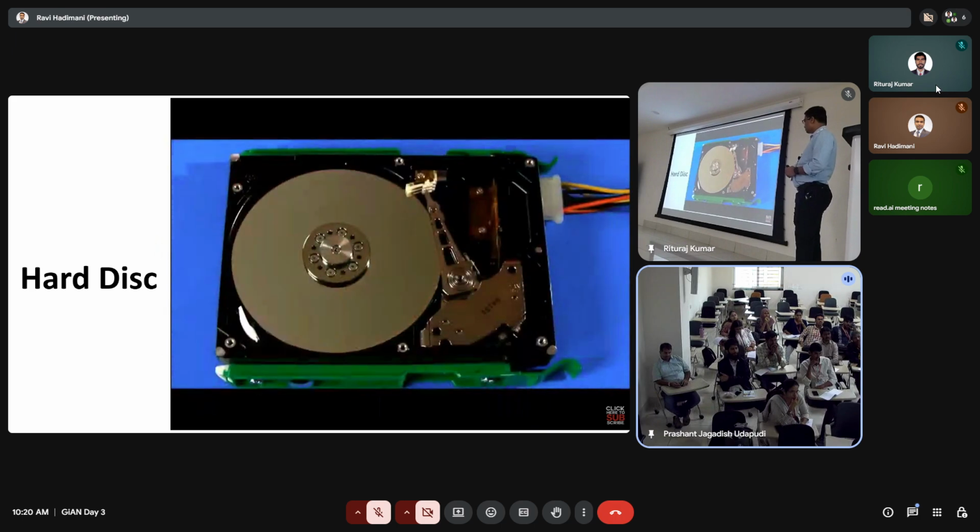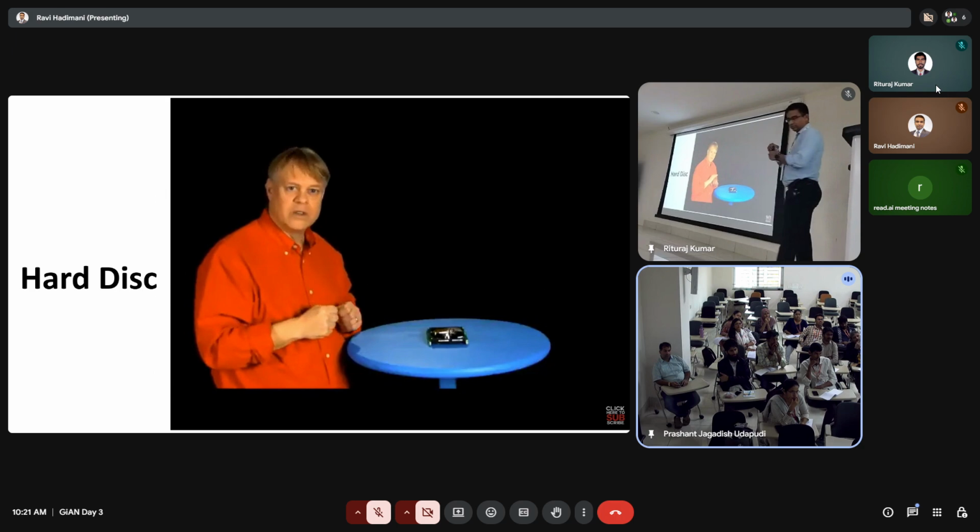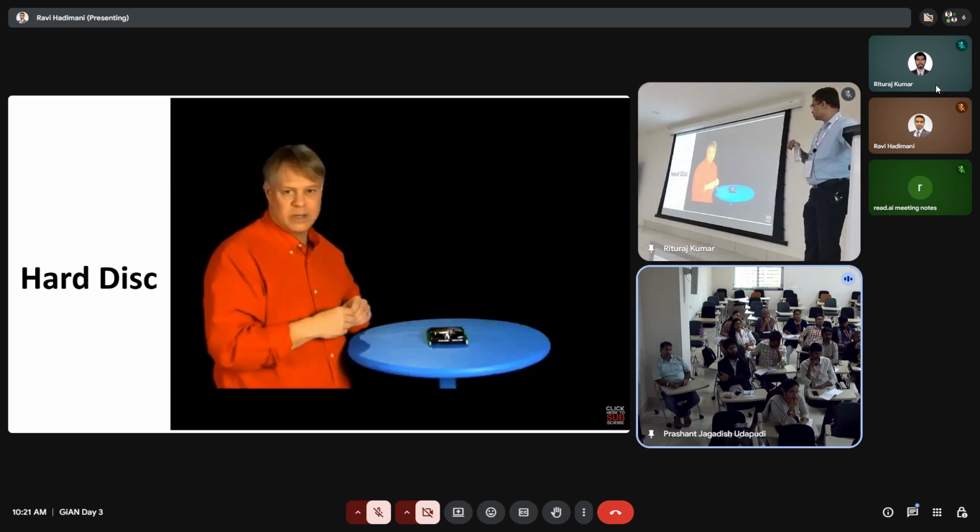As current flows in one direction in the coil, the force created by the permanent magnet makes the arm move this way. Reverse the current and it moves back. The force on the arm is directly proportional to the current through the coil, which allows the arm's position to be finely tuned. Unlike a mechanical system of linkages, there is minimal wear and it isn't sensitive to temperature.